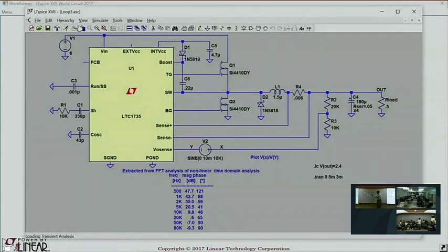And if I reset this flip-flop according to a quantity that is not current, from dimensional analysis alone I know that the transfer function from there to there is not a transconductance. It has to be something else. Okay? Now, what it actually is, there's some impedance here. Not much, basically negligible, but you should be aware that that would then make it exact if you had the right impedance to put there.